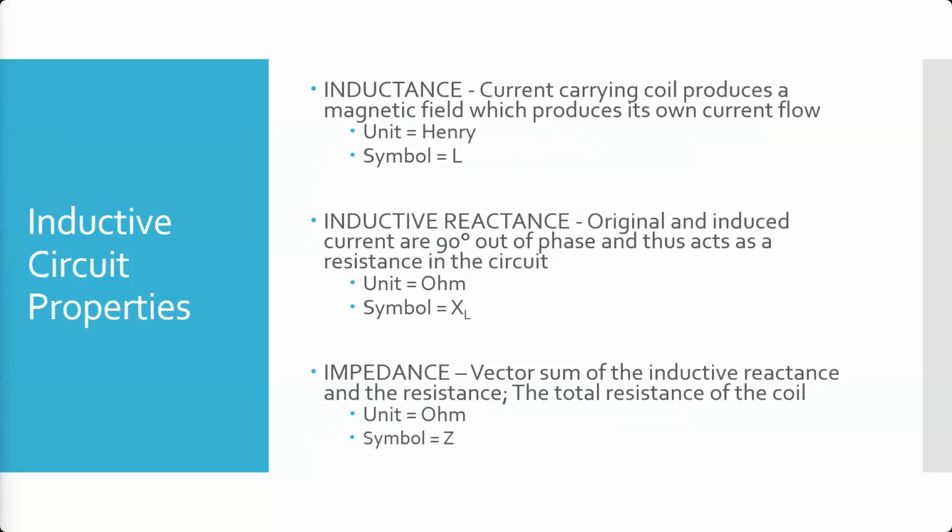It's going to be a portion of that current flow, the vector portion that lines up with the original current direction, or that opposes the original current direction. The portion of that inductive reactance that's out of phase, that's 90 degrees to it, isn't going to do anything to affect it. So you're still going to get a positive current flow. It's just going to push back and reduce it once that magnetic field builds up. And that's what creates impedance.